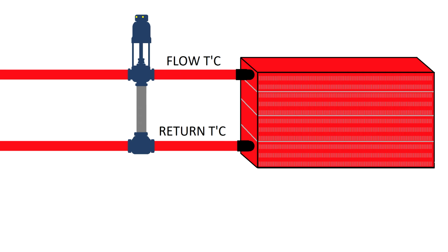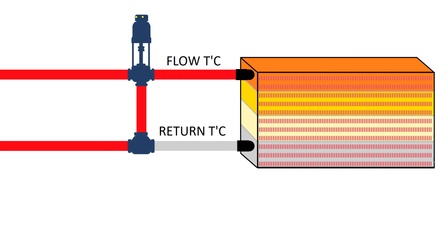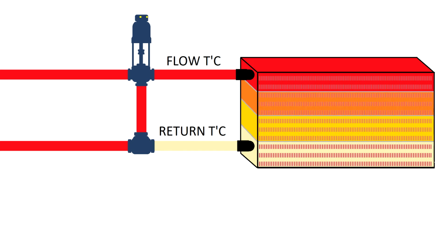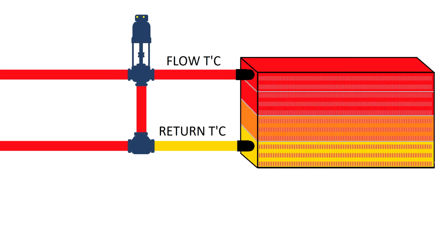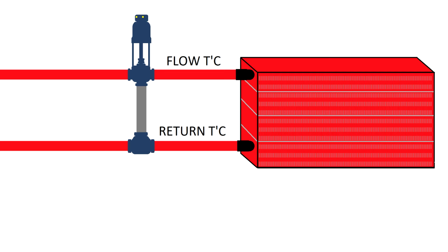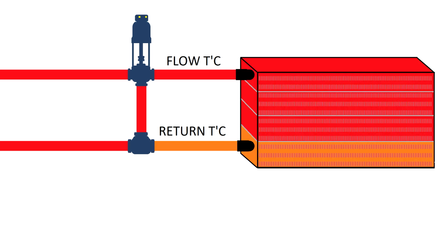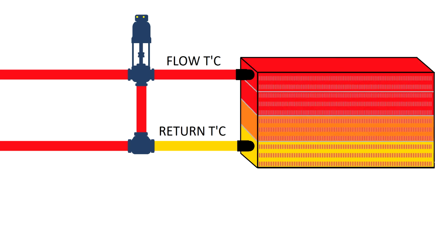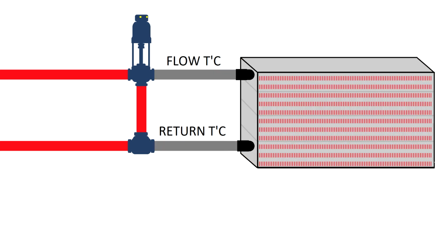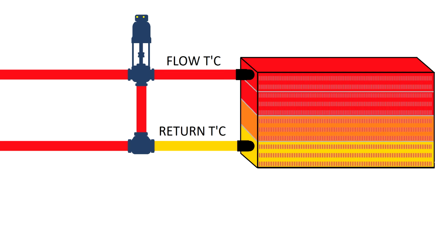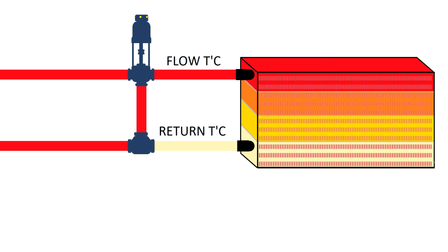When you talk about PID, things are changing. Now the valve will not open 100% or close 100%. You will control the heat exchanger capacity. A programmable logic control, a building management control, or a thermostat which has PID capability will allow the actuator to control the heat exchanger's capacity, which means it will progressively or partially open the three-way valve, allowing only a quantity of heating agent to pass through the heat exchanger.